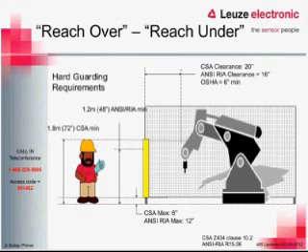So before we talk about our optical type solutions, we'll first talk about hard guarding. When we look at hard guarding, it's a little different than we do with our safe distance calculation on our active optoelectronic protective devices. Here we need to look at basically just distance and how far we can reach, how large are the openings, how tall is the barrier, things of that nature.